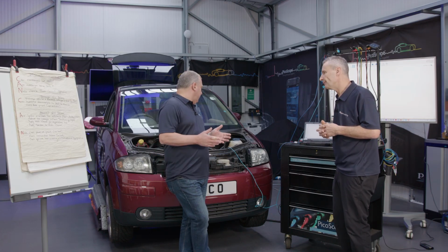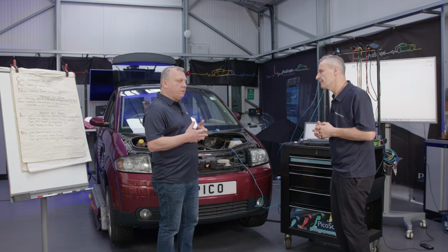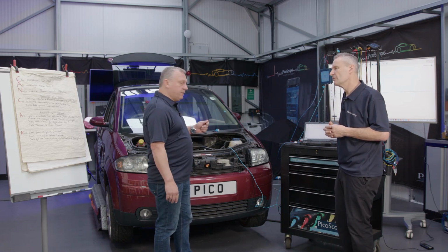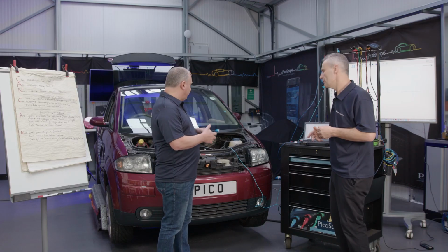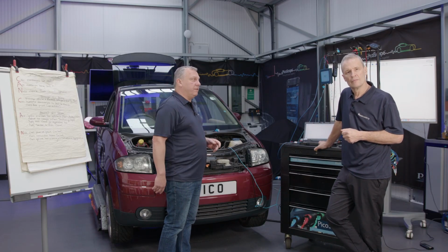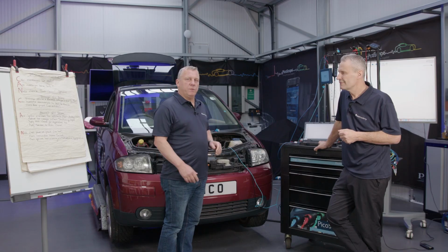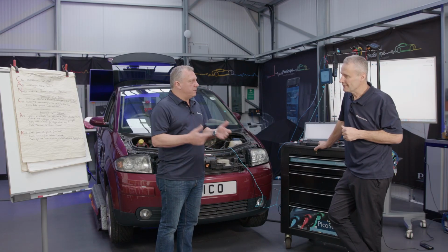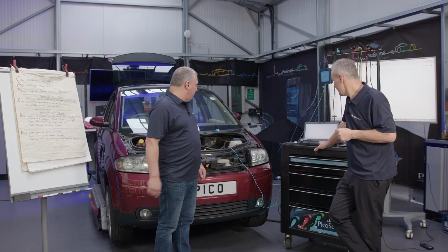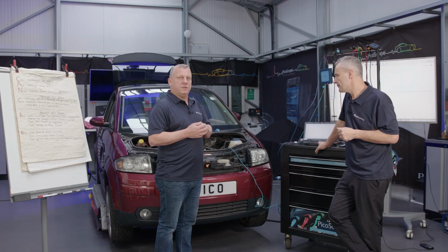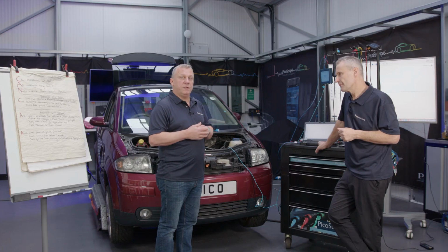No, but there may be people who believe testing for power and ground at the ECU is simply that, connecting a meter or a scope to the pins and seeing if you have a ground and a live there. But we discussed earlier on when we were doing the milliamp testing that the best way to test these things is loaded. Load the circuit. Now you may not be able to load the ECU if you suspect there's something wrong there, so you need to apply an external load, and that's what we'll go through now.